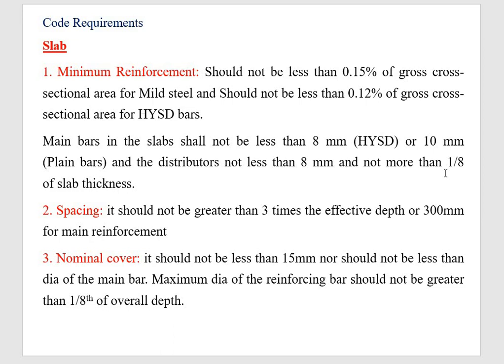Next is spacing. About spacing, it should not be greater than 3 times the effective depth or 300 mm of the main reinforcement.